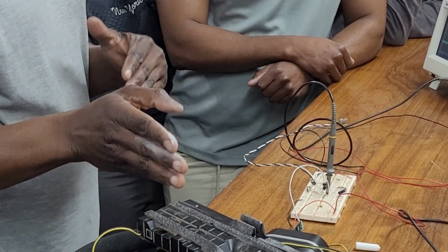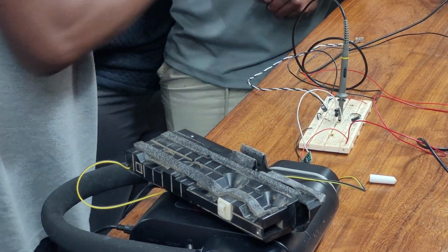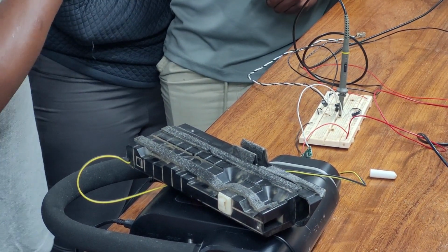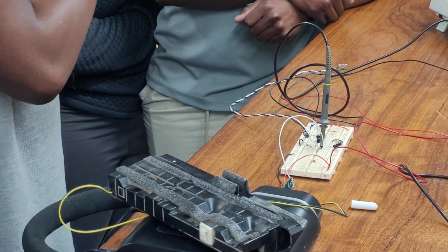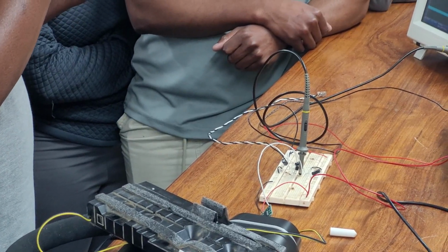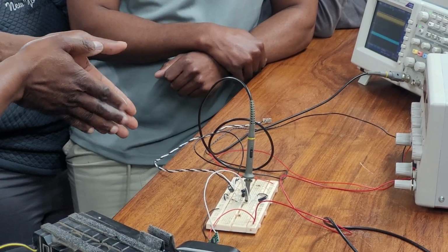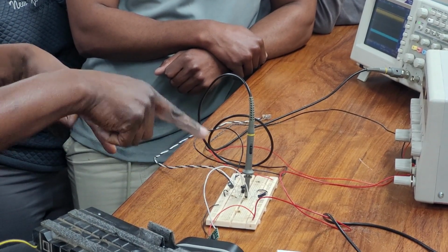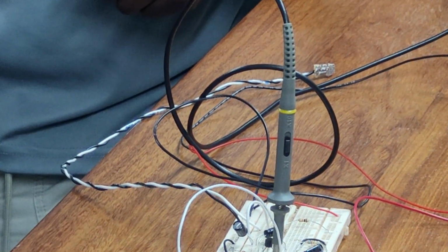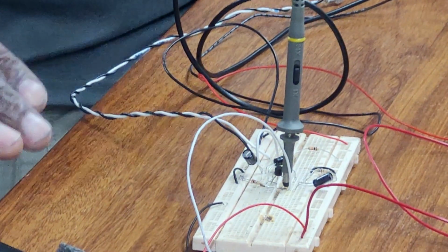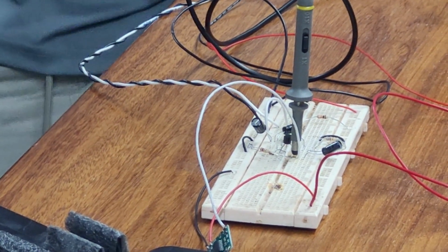The circuit between the input and the output oscillates optimally at 600 hertz. Okay? It no longer needs additional input. And the way to stop it from howling is to disturb that loop, to break the exchange of energy within that loop. So there's any number of ways of doing it. For instance, you can reduce the volume. I could have put a volume control here before it goes into the amplifier, just to reduce that volume. Or I position them differently such that the microphone no longer picks up what the speaker is doing.